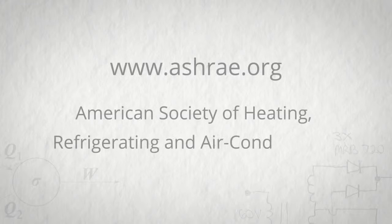Once you manage your airflow properly, the next step in data center efficiency is to increase the temperature of your cold aisle. And it's long been believed by many data center operators that the data center has to be cold to keep all the equipment at a temperature that it will run safely at. And in fact, that's just false. If you look at recommended guidelines from ASHRAE, they recommend running all the way up to 80 degrees Fahrenheit. And at Google, that's exactly what we do.